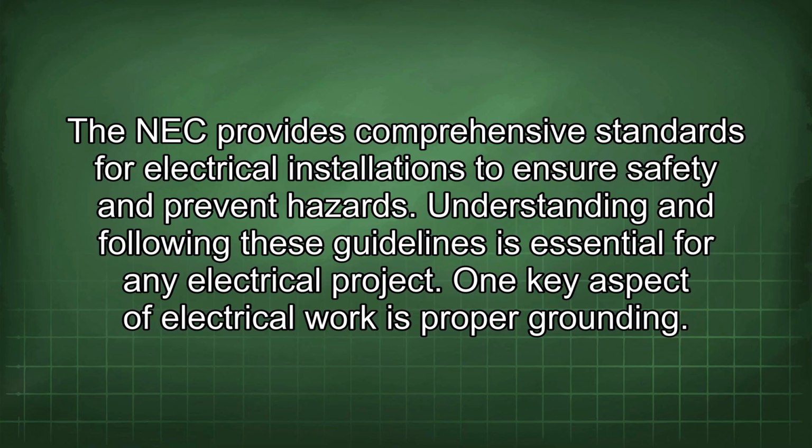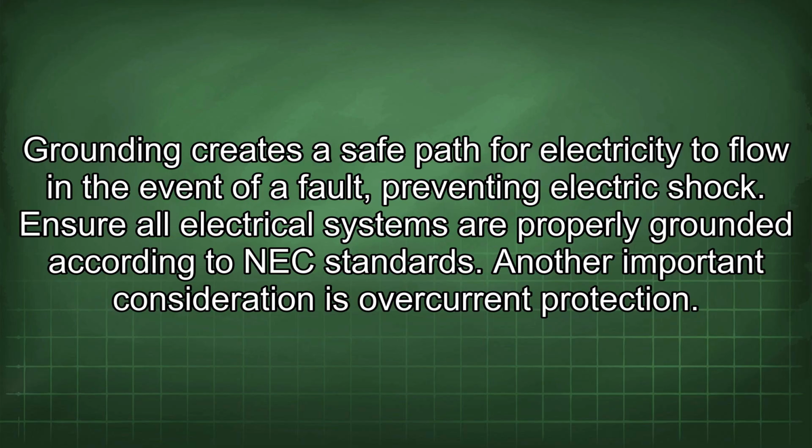One key aspect of electrical work is proper grounding. Grounding creates a safe path for electricity to flow in the event of a fault, preventing electric shock. Ensure all electrical systems are properly grounded according to NEC standards.